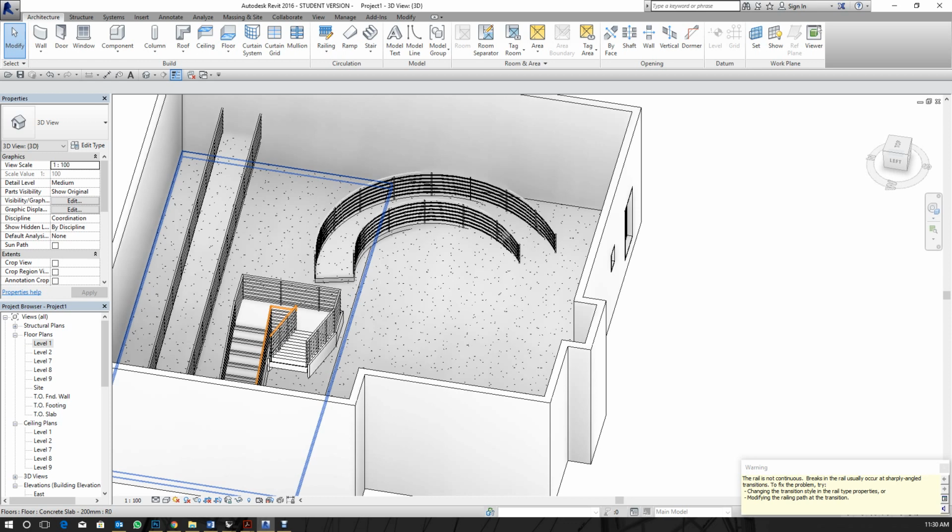The only challenge with that, and what I do to work around it, is when you import that kind of thing into Revit as a mass, you can't really make a drawing out of a mass. So what I do is I create a really thin wall and apply that to it, and I just call the wall elevator or whatever, and now I can include it in my drawing, like a wall of 10 thickness or something.